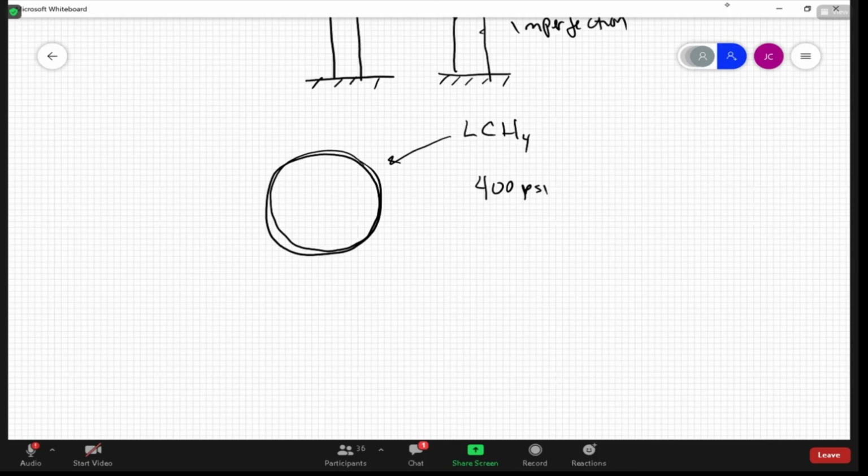And you guys know how to do this, right? We've got a pressure vessel. We were looking at making this out of titanium, a titanium welded spherical pressure vessel. They went through and did the allowable stress, the actual stress, which is pressure times the diameter over twice the thickness.